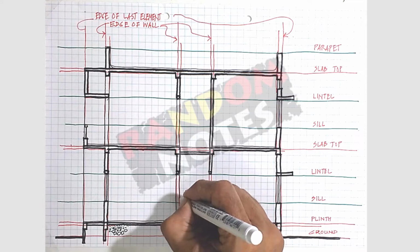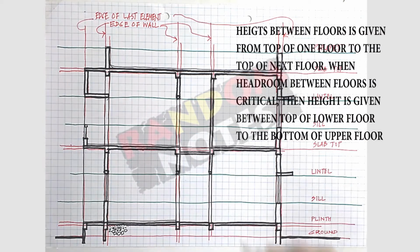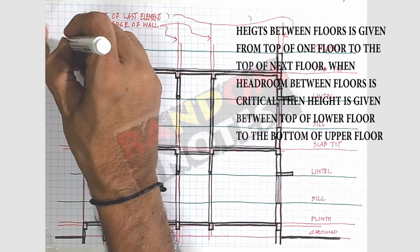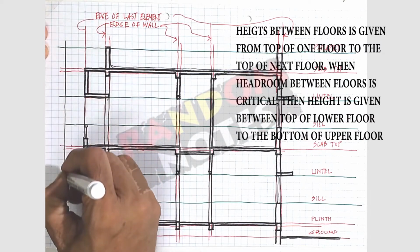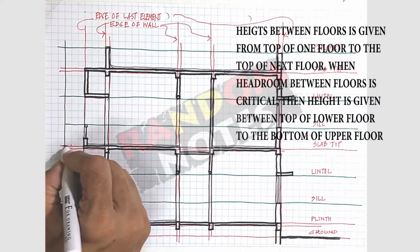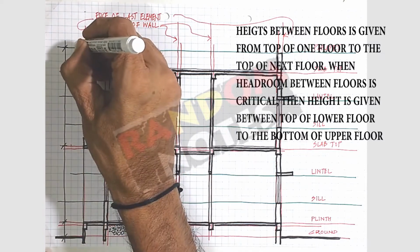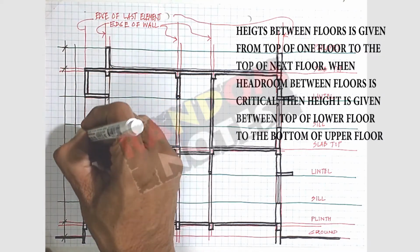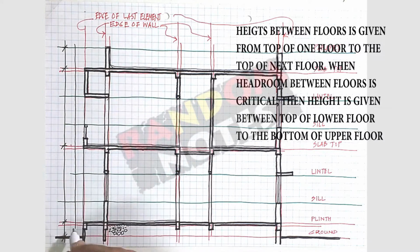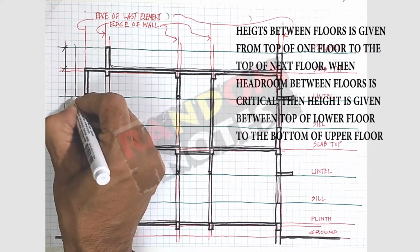These are the edges of the door jamb visible at the back. In a section, the important dimensions are that of the datum levels from ground and the floors. The important dimension between two floors is from top of one floor to the top of the other floor. This is known as floor to floor dimension. Then within floor to floor dimensions, you may break up the dimension into smaller important parts.